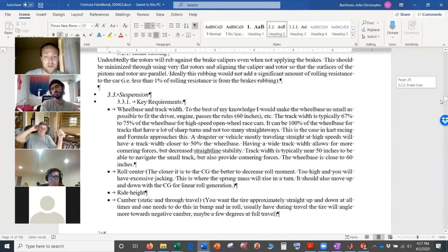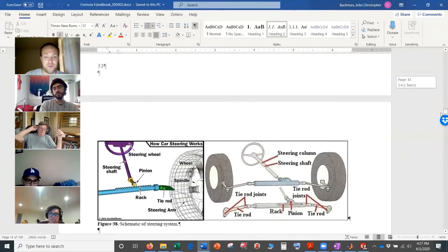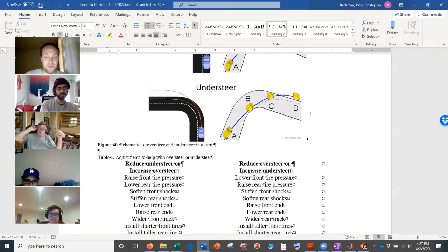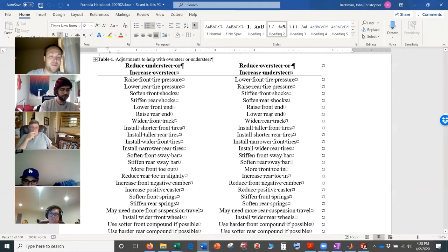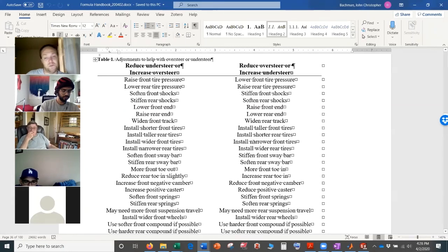So let's see here. I think another reason why they would favor the understeer or oversteer is because there's a thing called snap oversteer. It's probably when you have a really well balanced car and you're hitting a corner and you hit the limit, but if you're not experienced, you don't really see that limit, so you might just pass it and it'll mess you up. And I think that's like a 50 balance, like a neutral steer, right? Yeah, it's like everything's even. Yeah, though it's a little bit different too, because I don't even know if you'd consider it oversteer, because they're losing traction in the back. They have like no traction.